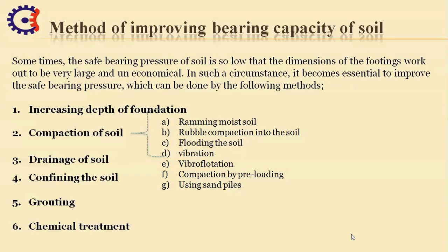Grouting, this method is applicable for soil where there is a presence of pores or cracks, etc. underneath the foundation. In this method, poor soil bearing strata is hardened by injecting cement grout under pressure because it seals any cracks or pores, etc. For proper distribution of cement grout, the ground is bored and perforated pipes are introduced to force the grout.